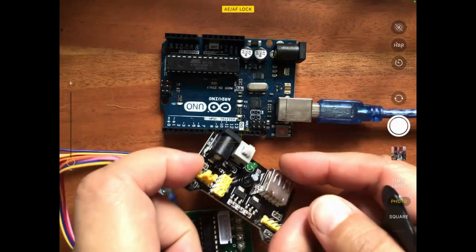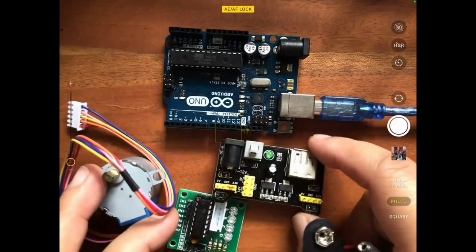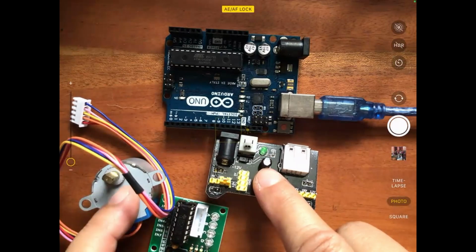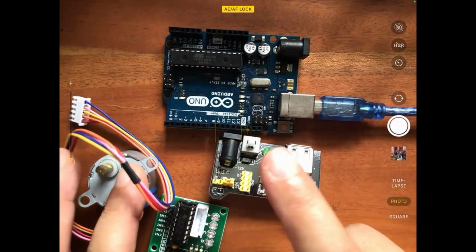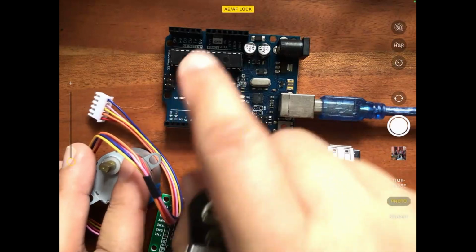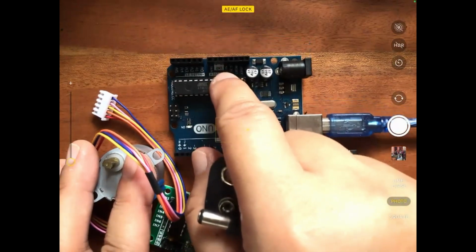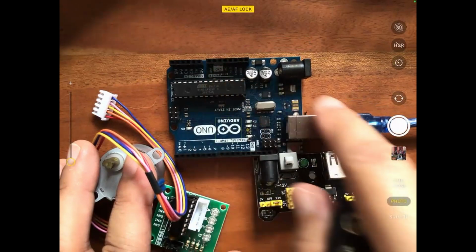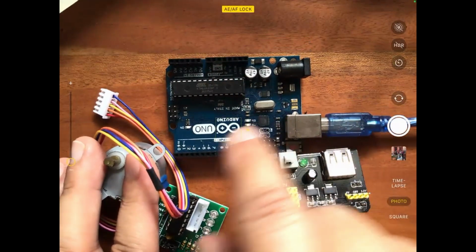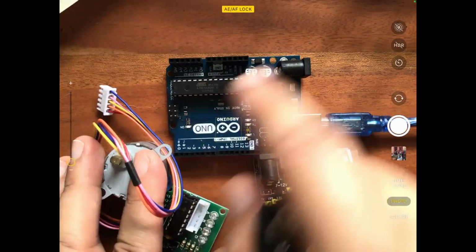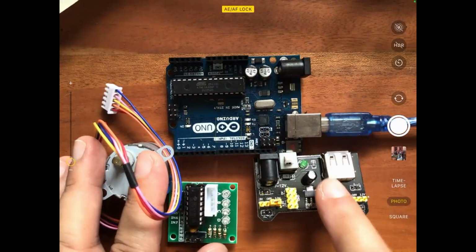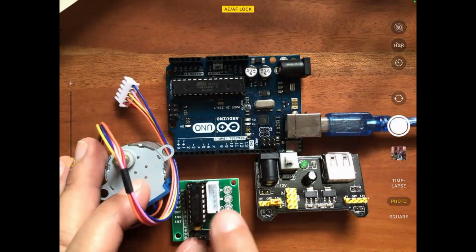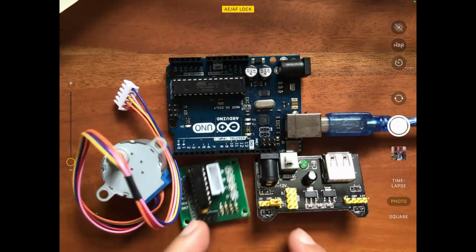Okay? So, these are all you need. This is optional. Remember please, if the thing that you're carrying or rotating with the motor is light, probably you won't need this. It's enough to draw the power from the power supply of the Arduino. However, note that pag bubigat yung dala-dala mo, forget it. Use a separate power supply for the motor.